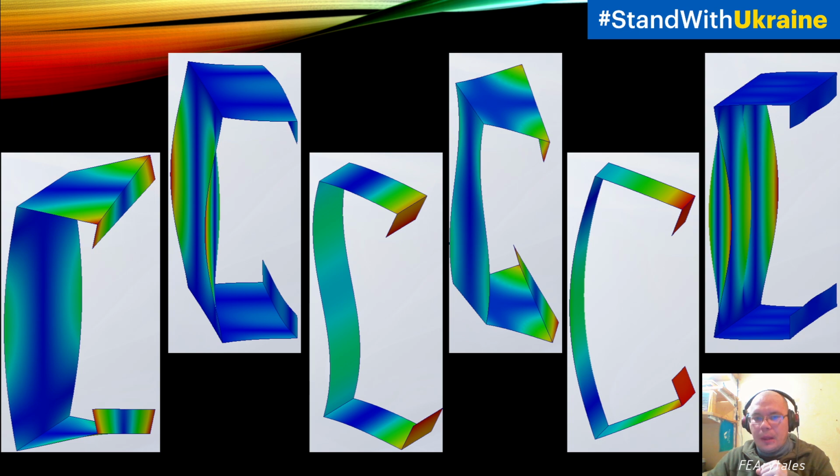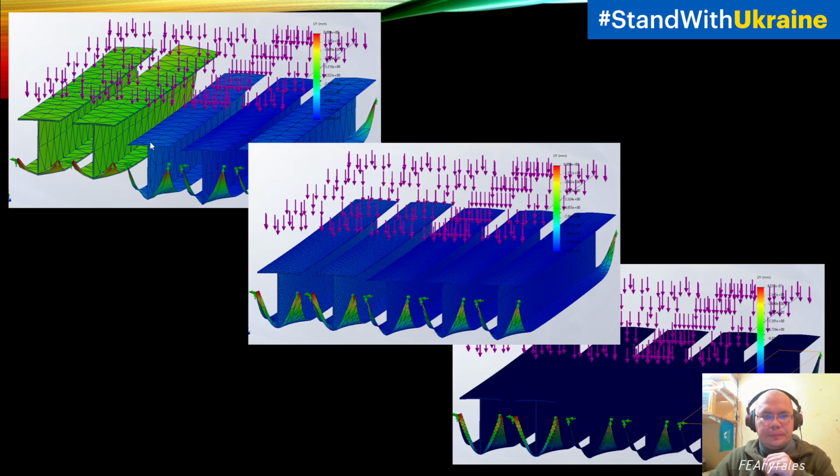So per size. This is an example from the SolidWorks simulation course, and this is our solid geometry created in one way, and plate geometry also created in a different way. And we can see that our shell plate geometry deformed the same, with the same character, the same type and the same values with any mesh, if we use a plate element with mid-size. But if we talk about solid mesh, we can see that we need at least 5 elements per this plate to describe good behavior.